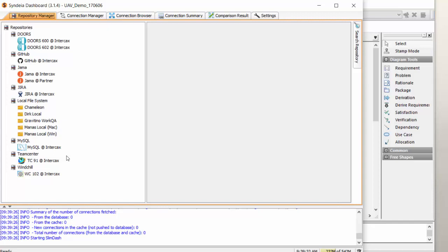If we launch the dashboard from the top-level package, we will be able to make connections to any SysML element in the model. We can also launch from lower-level elements, but then we will only be able to make and use connections to that element and elements under it in the browser. That can simplify our view of the model, but it requires the user to reset the scope of the dashboard using the goto command for connections to other SysML elements.